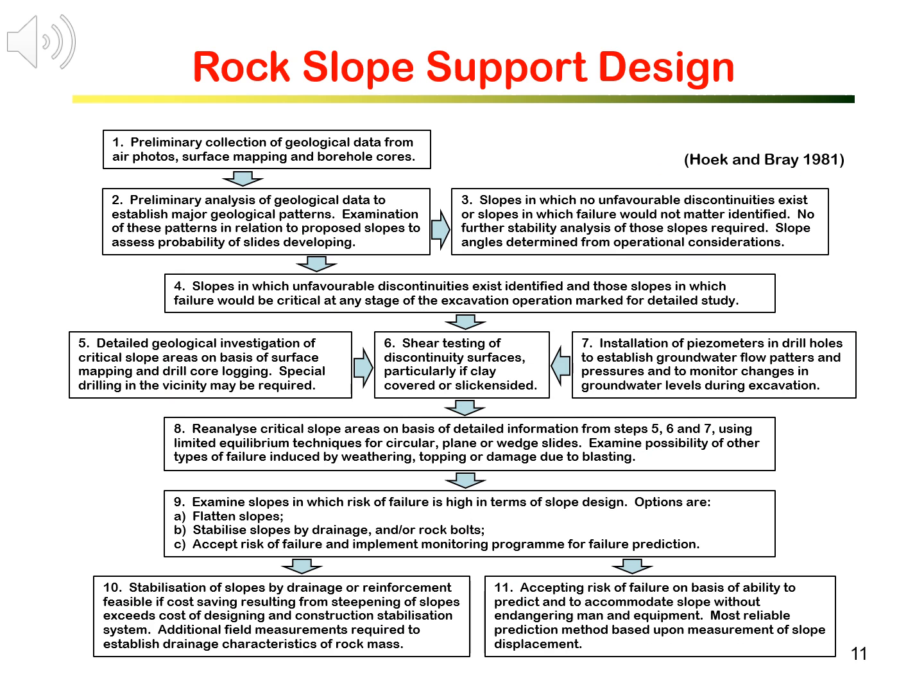I showed this flowchart briefly in session 2.2 earlier. It is now perhaps worthwhile for you to go through the flowchart step by step to capture the important stages of rock slope stability assessment and the slope support design. You can see that steps 1 to 6 are very much focused on understanding the geological features and the structures of various discontinuities within the slope, as they are the most important features associated with slope stability and failure.